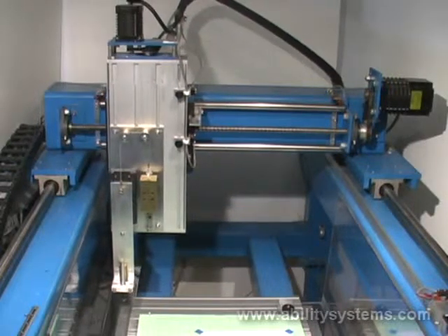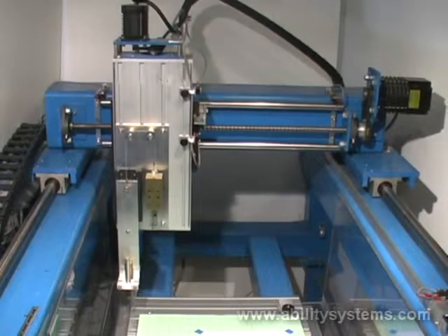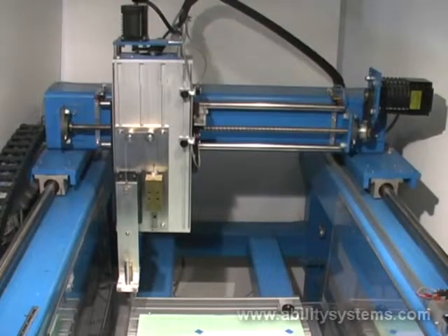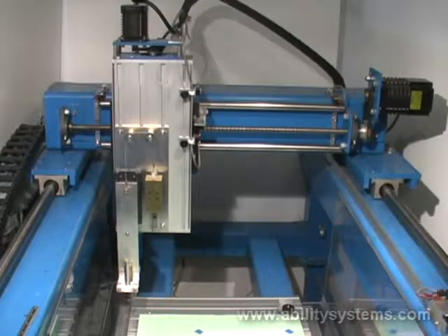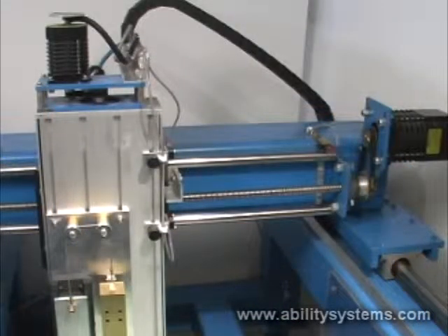Instantaneous motion is used to accurately stop on the pulse that causes the switch to be activated. Accelerated motion is used to rapidly withdraw the stage from the switch to a position that will be referenced as home. Here is a way external switches are used to initiate machine motion.